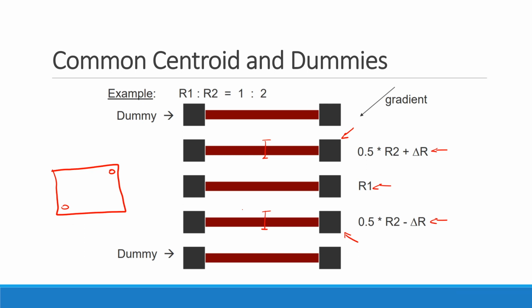These days, it's maybe not quite as important, because for most things you work with, there's so much stuff packed into a small area that if there was any really big gradient, the chip probably wouldn't have worked. Okay? So a lot of the layouts you'll see today won't exactly follow this layout style, because if I have more than just one or two elements, pretty quickly it gets to be kind of a pain in the ass to really make this happen, right? Because you have to do all these weird interleavings and sharings and things like that. I mean, it's not too bad, but it just gets annoying, okay?